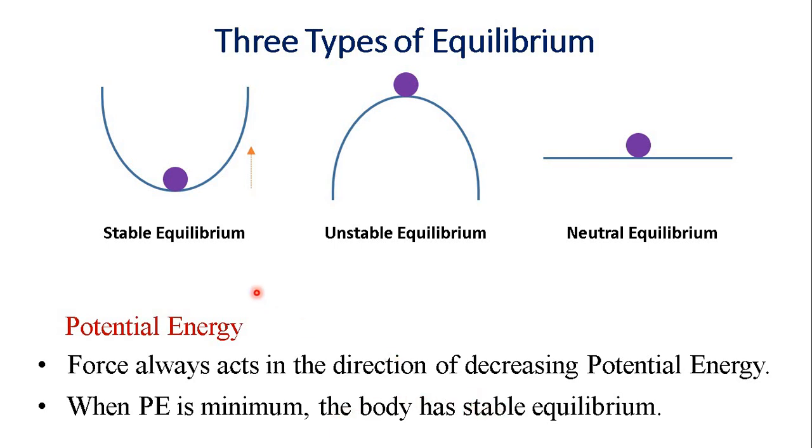Okay, so now let us try to understand the principle of minimum potential energy physically with an example. I have this spring that is attached on the left to a rigid support, and on the right end a horizontal force F is acting in this direction, and this green dot here is called a node. Here this node is nothing but a representation of a point that is common to this spring and this force. Now we know that when force F acts at this point, it tends to stretch the spring and this node displaces to the right.